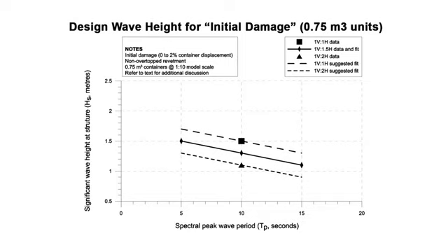We shift to a 10-second wave, so these are higher energy waves. The damage threshold drops to around 1.3 metres. You can see very little damage, maybe 1% here, usually about 4 or 5% here. We shift to 15-second waves. These are high energy ocean swell waves, with much more power in the waves. The threshold for no damage drops to about 1.2 metres. In some circumstances we're getting quite high damage, 15%, which is failure of the structure. So we always set the design curves to this no damage threshold.